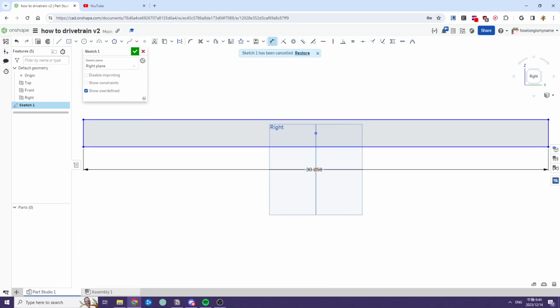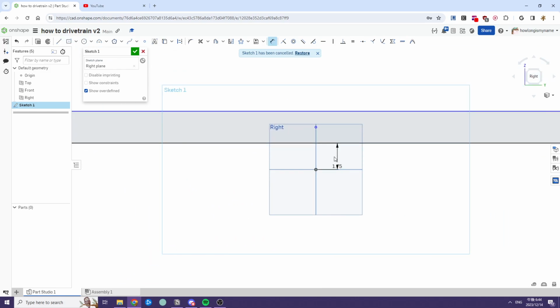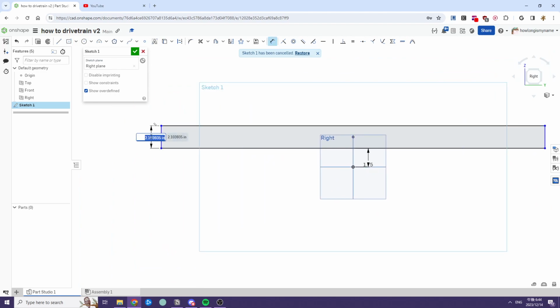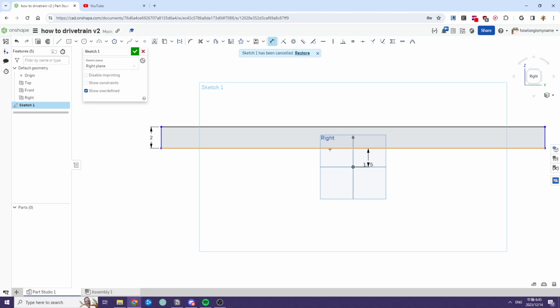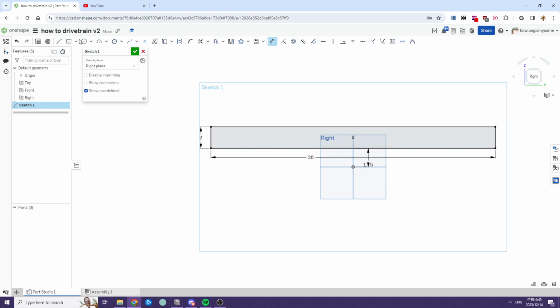The master sketch is important because it allows us to get a side visualization of all of our mechanisms and our drivetrain and everything in one place, which means that we can see where they're going to be placed together and allows us to make sure we have space for everything. So once we make the tube for our drivetrain, we want to make our bumper. If we're making an over the bumper intake, this is going to be useful.